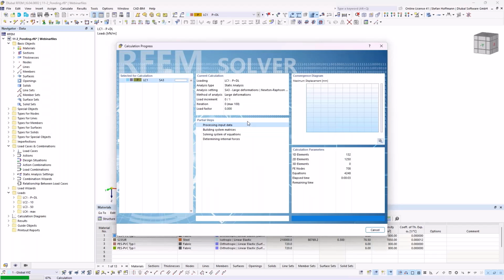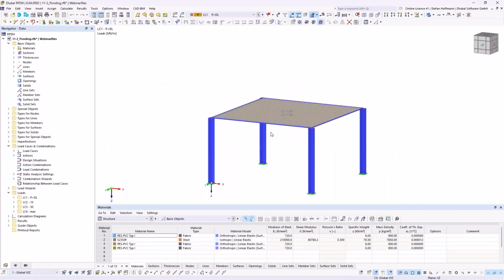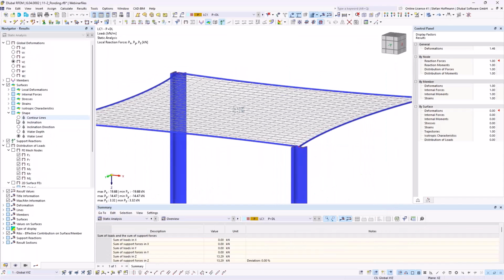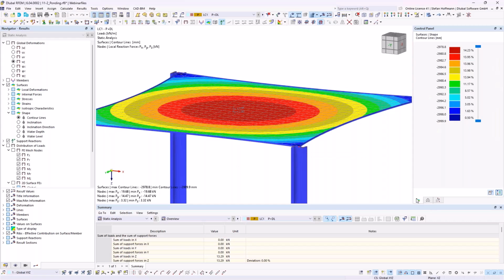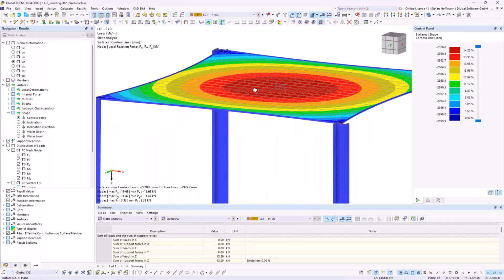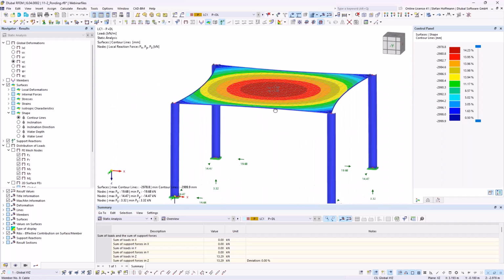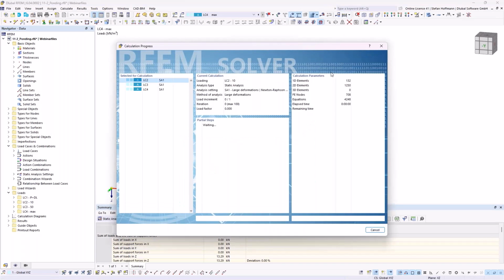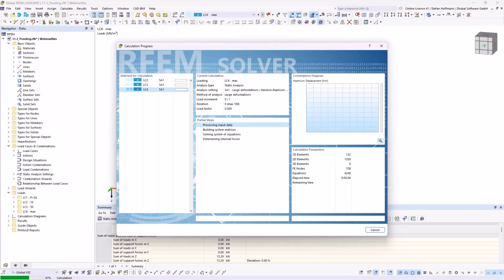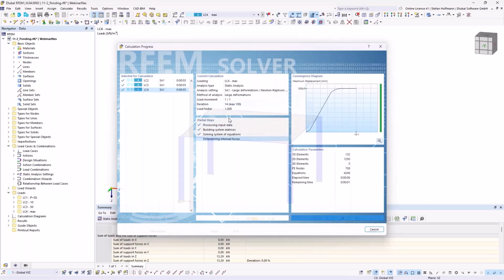So due to the minimum dead load, there will be some starting shape, which you can check with the contour lines. So this is a 3-meter member height, and we have about 2 centimeters of deflection already in the Z direction. If it now rains, I've chosen 1 times 10 millimeters, 50 and a bit more, so the full way. You can now see it a bit better because it's quite an easy structure to observe how the rain will then fill your construction.